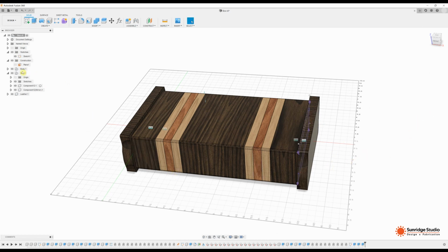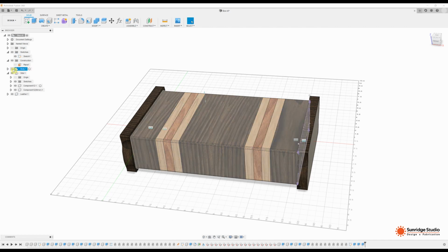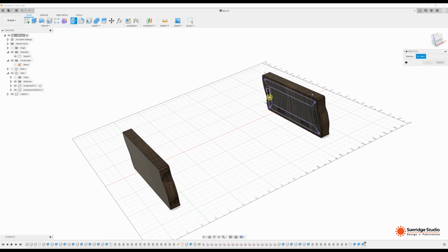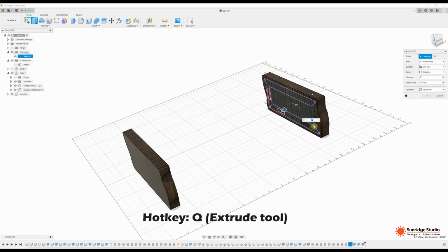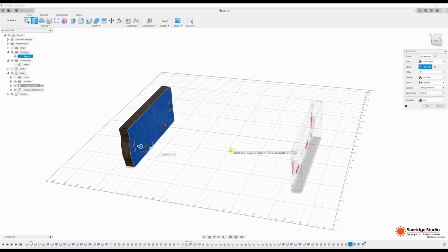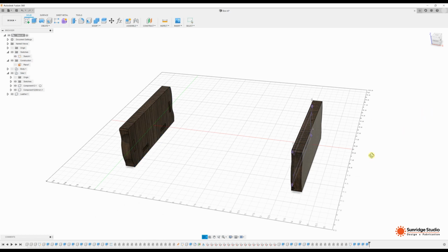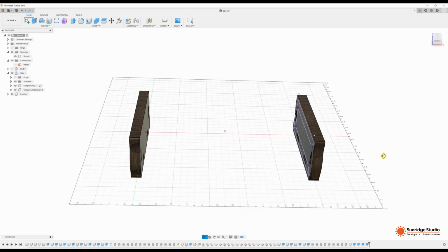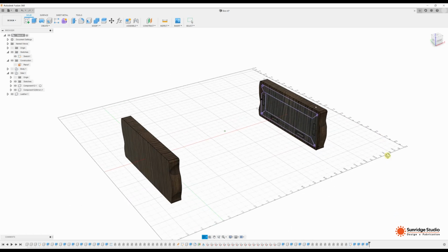And then we turn off the body component for now, and we use the same sketch to create mortises on the left sideboard. So we select from object as our start and select the surface, same distance, and also cut operation. Now we have mortises on all of our boards, the sideboard and also the body boards.